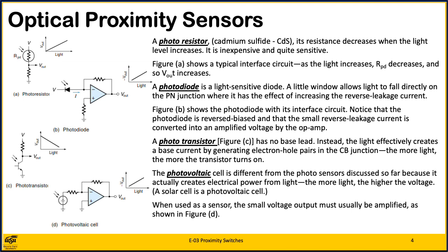Optical sensors enjoy the advantage that neither the light source, the object to be detected, nor the detector have to be near each other. An example of this is a burglar alarm system. The light source is on one side of the room, the burglar is in the middle, and the detector is on the other side of the room. This property can be important in a case where there is no convenient mounting surface next to the part to be measured. On the other hand, keeping the lenses clean may be a problem in some industrial situations.